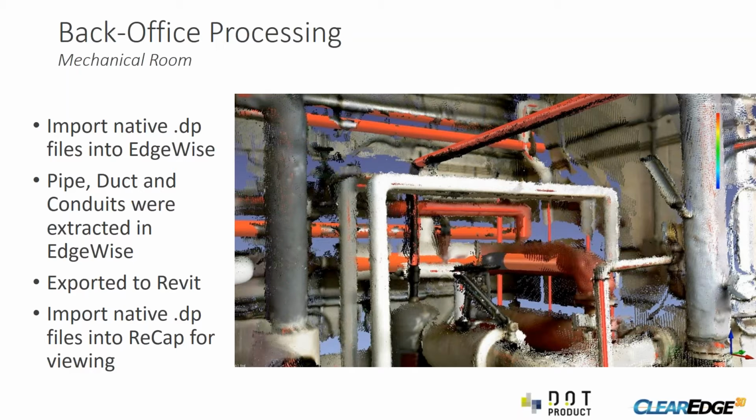After we were done with all of our capturing out in the field, we came back to the office. We prefer to use the .dp files that are native to the DPI-8 scanner, and they imported to EdgeWise great. We extracted all the piping, ductwork, and conduits through EdgeWise. We set it to run overnight just because of the time. It was very simple. It's a hands-off kind of application for the initial portions of it. After we did our QA/QC within EdgeWise, we exported it to Revit.